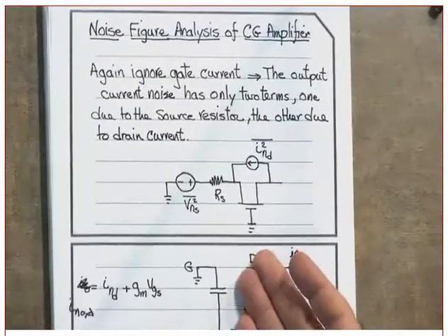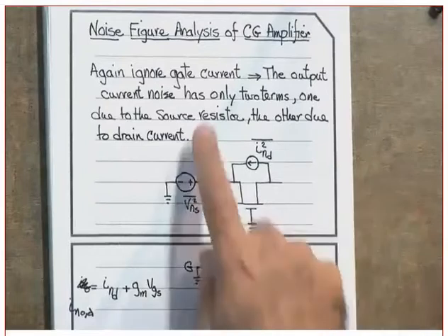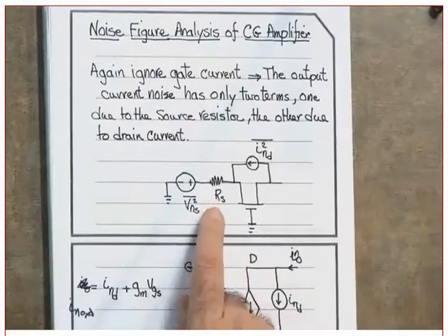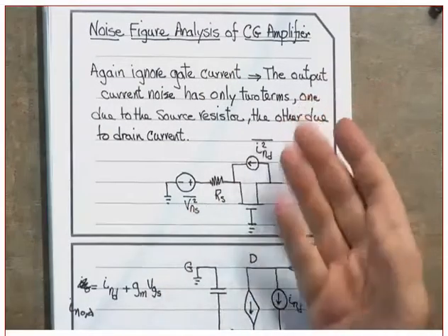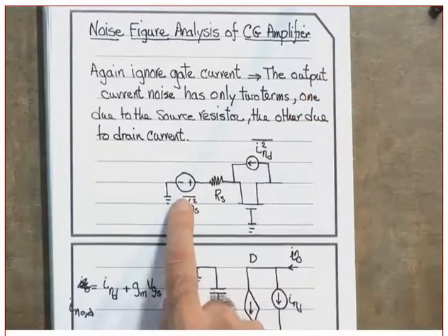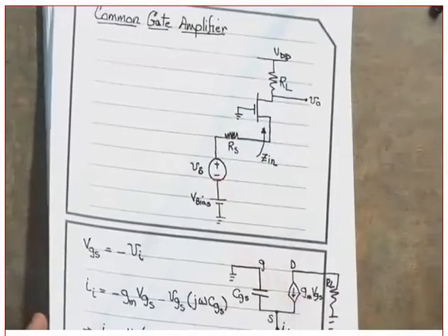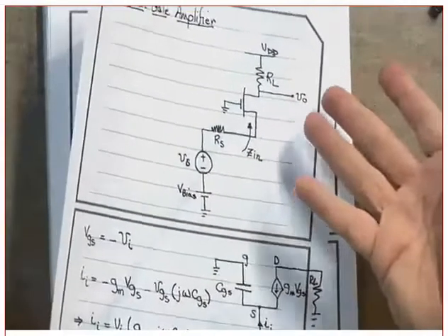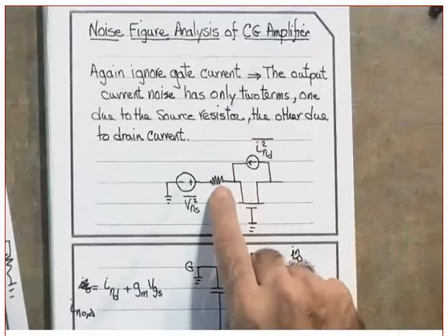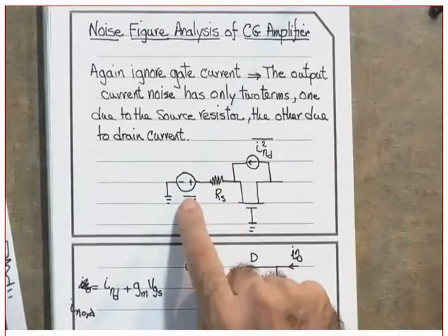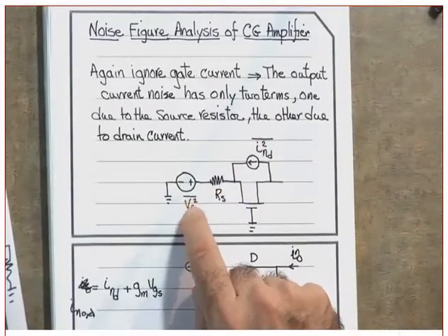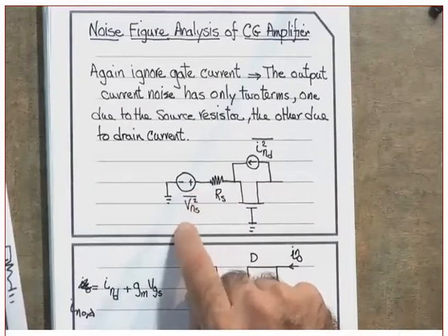Did we reach this or not? But in any case, this is the noise figure. I wanted to see what the noise components are. This is due to the source. You notice, by the way, this Vs is gone. Why? I don't care about the Vs. This is just the noise. So this is now a noiseless resistor, and this is the Thevenin equivalent noise voltage. Clear? Mean square, so it's a power.